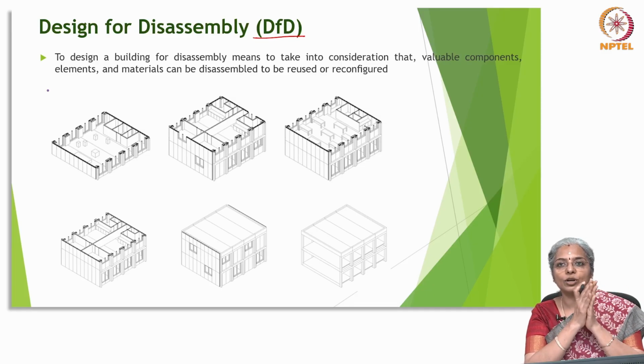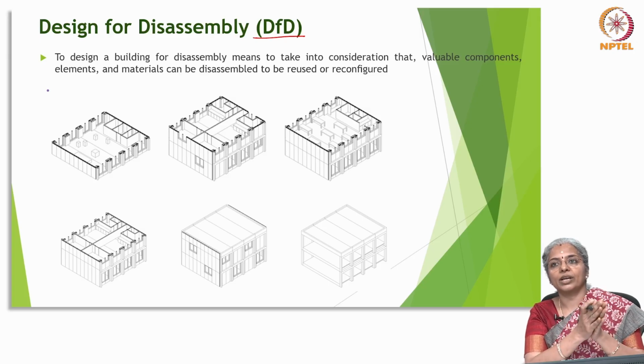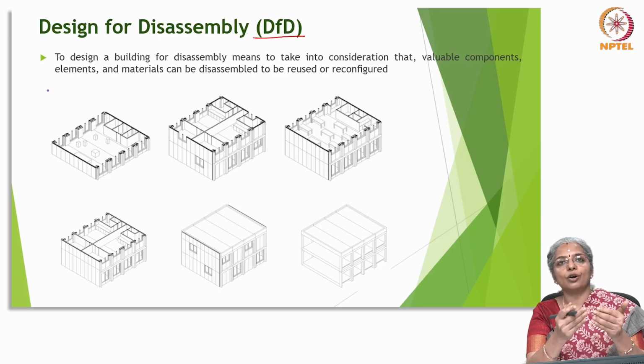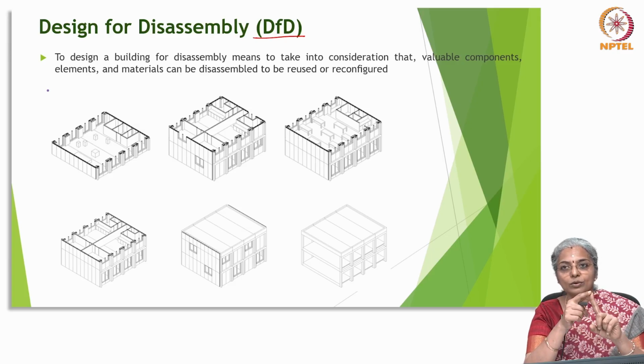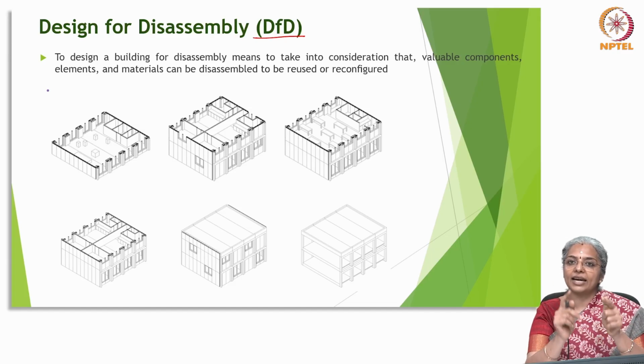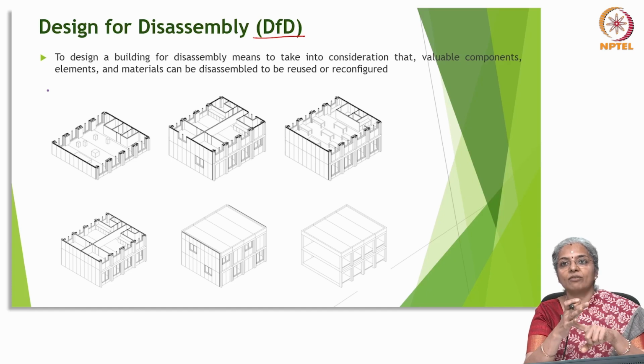So, to design for disassembly is actually to create products with the intention of minimizing their value loss at the end of life. In construction, this will involve designing a building with consideration for how it will be dismantled and the recovery of the materials at the end of its useful life. This will allow for recovery, reuse or recycling of materials and its components. Thus, it will reduce waste as well as reduce the environmental impact.